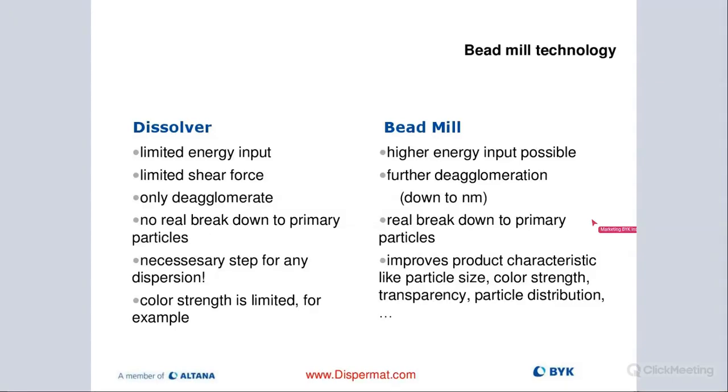So you can't take your material and go straight to a media mill. That would probably lead to clogging of your screen or dynamic gap, and then you're not going to have any flow of your material. So it's very important that you first pre-disperse before you start the milling. And then again, as you saw earlier, you're going to have problems with the quality of your product.